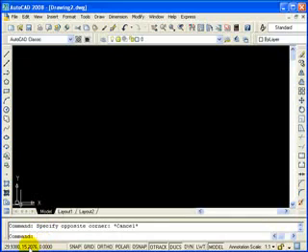At the very bottom, on the left-hand side, on your status bar, in the bottom left-hand corner, you'll see your coordinates, and that is the coordinates of where the crosshairs are in the Cartesian coordinate workspace, which we'll touch on a little bit later. There are some options here for turning on some of the AutoCAD options as you're drawing. You can click on these as you're working. O-snaps, ortho, and things like that. We'll get into some of these other options as well.